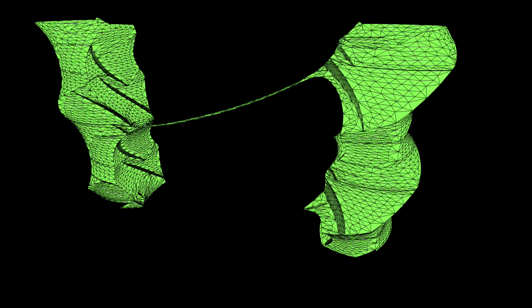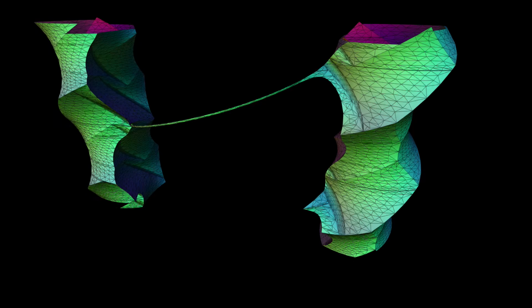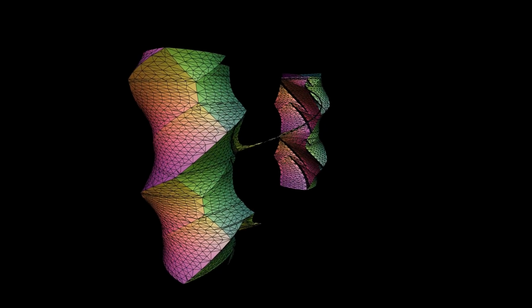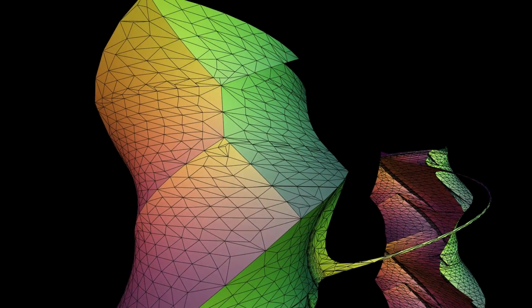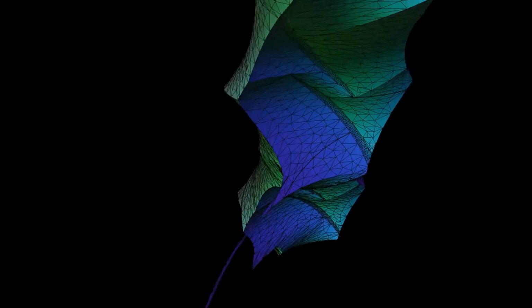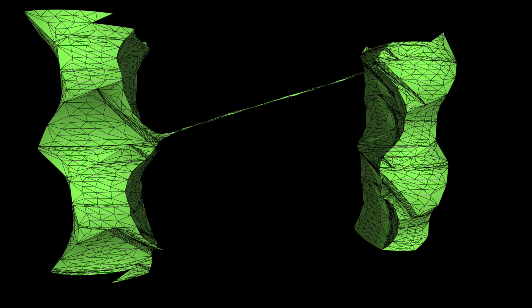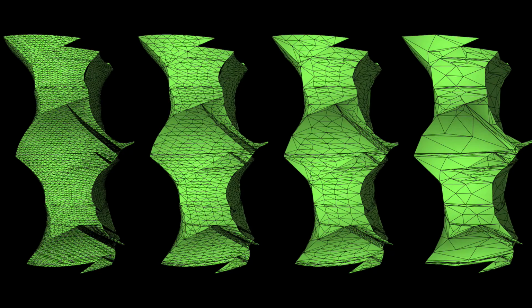While we have an exact trigonometric representation of the surfaces you see in 3D, some processing is required to actually render it on screen. For interactive graphics, the standard approach is to rasterize polygonal meshes, so we approximate the surface using triangles. The normal vectors for the vertices of each triangle are calculated from the exact representation, not the triangulated one, so the smoothness is preserved even with a coarser triangulation. Here you can see several triangulations of the same surface with varying granularity. Notice how the shading and overall structure remain similar, even with many fewer triangles.